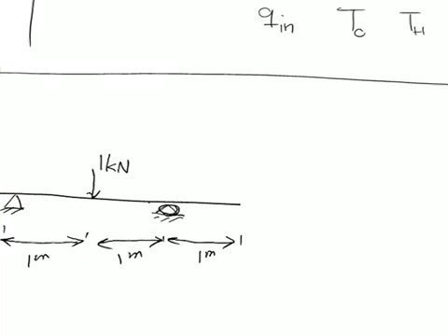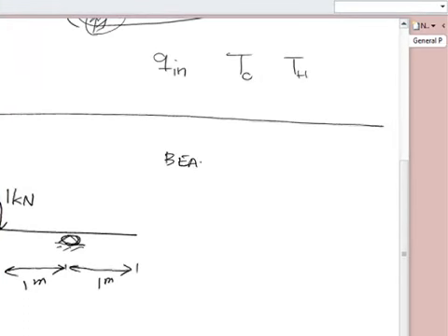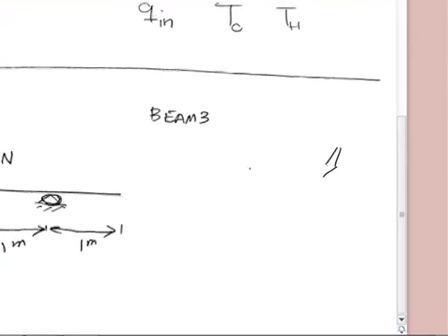Basically, what I have to do is to define an element first. For this case, I'm going to be defining the element BEAM3, which is a very basic element in ANSYS, which I've heard some newer versions of ANSYS are not supporting anymore. There is an alternative way, which I will explain later in future examples and tutorials. For this beam, I'm looking for a square cross section of 12 by 12, let's say meters or units.